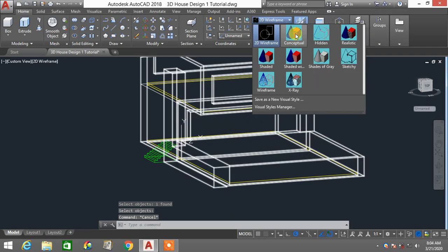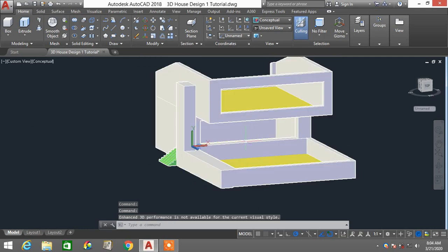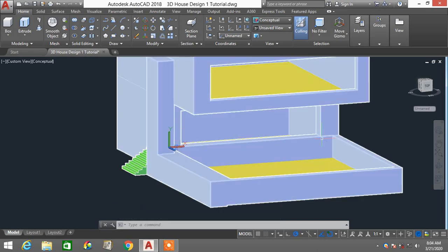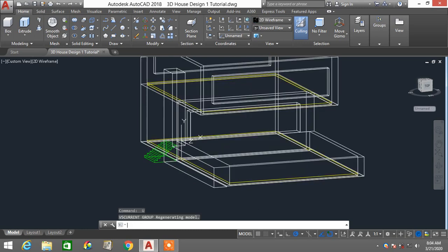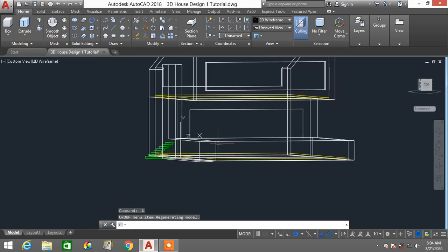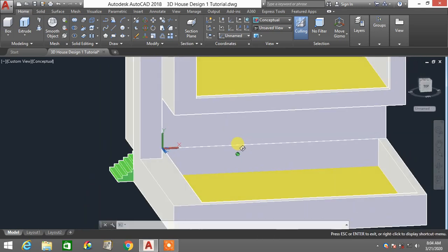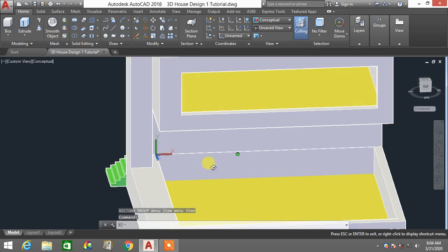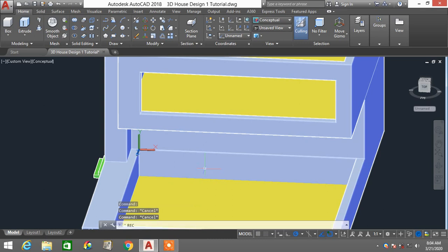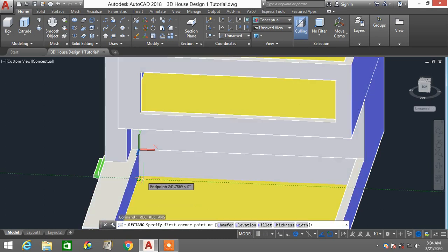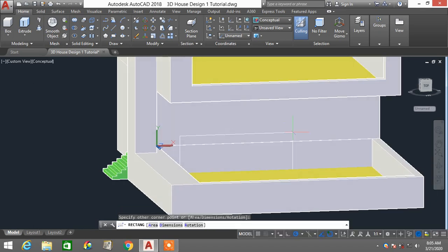If the press pull didn't go as expected, right, you can always choose the subtract command, but actually I have to subtract until here. So I'm going to undo this first. So the rectangle should be from down here until to the top. So I'm going to type REC, enter, and take from this particular point and shoot up the rectangle until here.